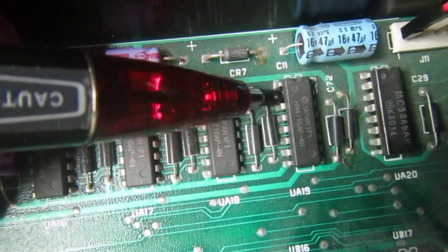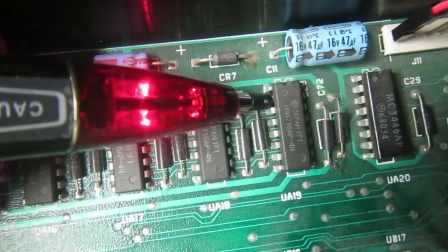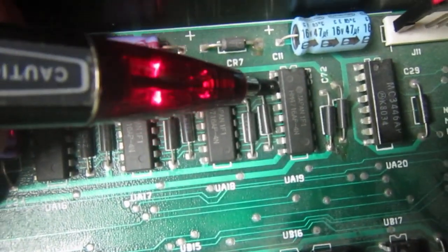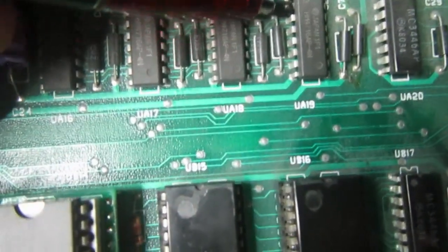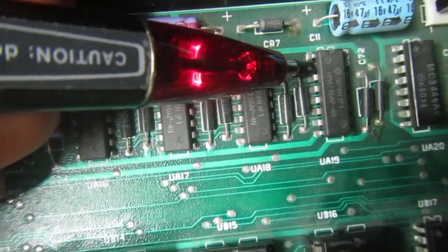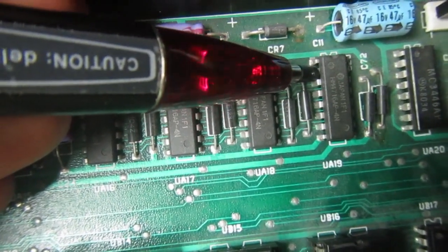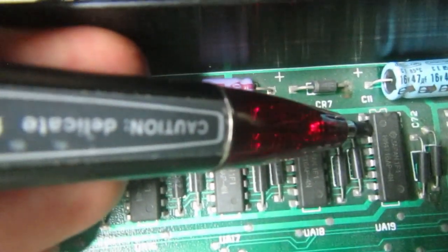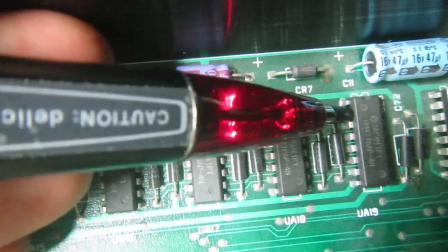And it starts flashing as the screen gets written. So this RAM chip is conflicting, even if it should not be enabled at all. It should do nothing at this moment. But you can see the data line is getting current spikes.